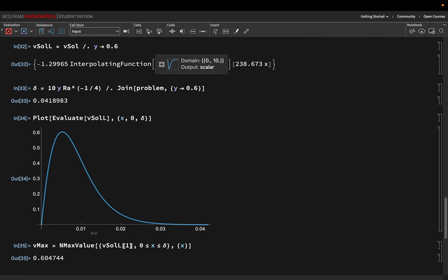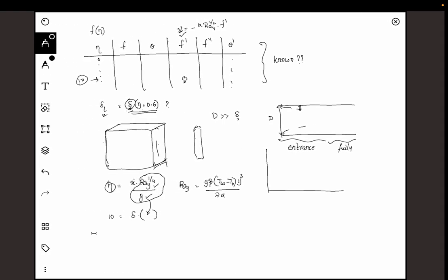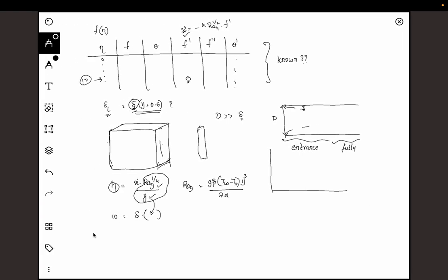There can be other questions you can ask from this. For example, you can ask what the shear stress acting on the wall is. How would you go about calculating that? It is again straightforward. All you have to do is calculate del v del x at x equal to 0, and that should give you the wall shear stress. Any other questions that you have, you will be able to solve once you know these values. We should be able to back calculate from them. Are there any questions?